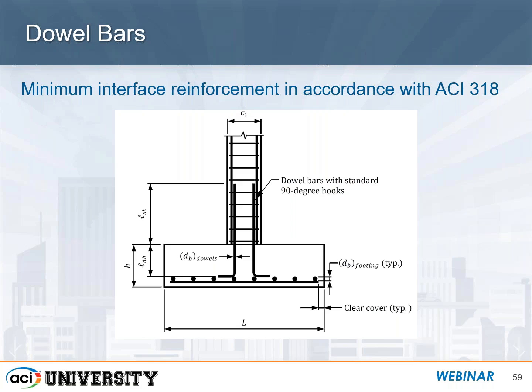Should the engineer check for section capacity in relation to tolerances? Or are the tolerances so small that they really don't make a difference? Bill, that's a very good question. Basically, with ACI 117, if you're within the allowable tolerances given in ACI 117, it's safe to say that you don't have to go back and check your structural members for strength or serviceability.